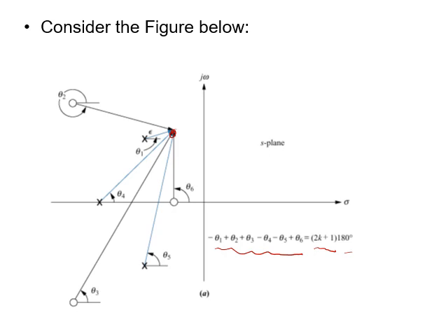Let's go to angle theta 1. Theta 1 is the angle of this pole toward that point, this angle. So we are going to say minus theta 1. How about theta 2? Theta 2 is this point, this one. The angle of theta 2 starts from here up to this point, that's the direction toward this point. Now, the sign of theta 2 is supposed to be plus, because we said angle of zeros minus the angle of poles.